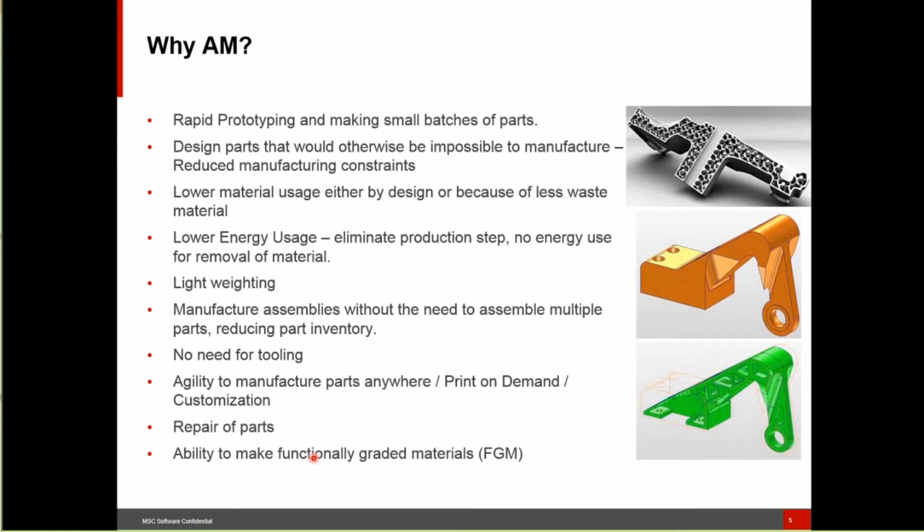So why additive manufacturing? A lot of this came out of the world of rapid prototyping. So additive manufacturing allowed us to make very efficiently small batches of parts. And the reason for that was additive manufacturing does not require tooling. So you don't need to build dies, you don't need to set up new hardware. So if you're only interested in a few pieces, additive manufacturing was very beneficial. Of course, one of the things we want to do is move from rapid prototyping in few batches to more production orientation.